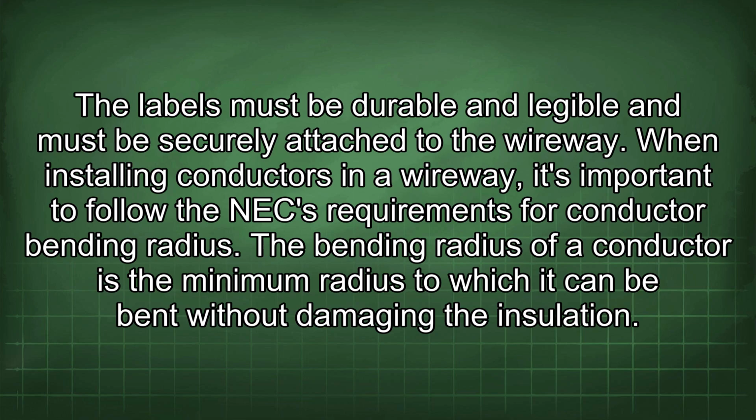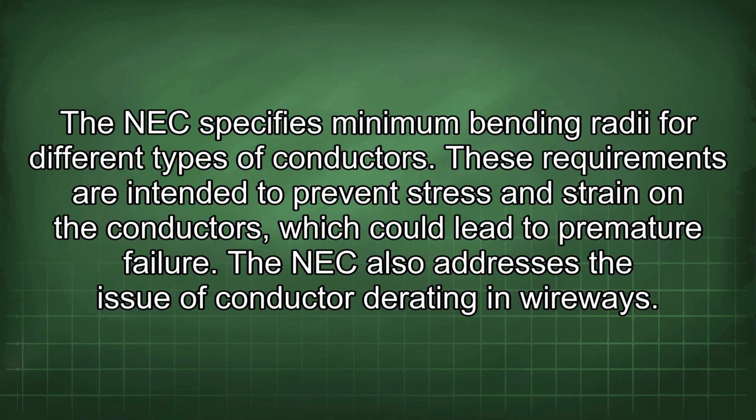When installing conductors in a wireway, it's important to follow the NEC requirements for conductor bending radius. The bending radius of a conductor is the minimum radius to which it can be bent without damaging the insulation. The NEC specifies minimum bending radii for different types of conductors. These requirements are intended to prevent stress and strain on the conductors, which could lead to premature failure.